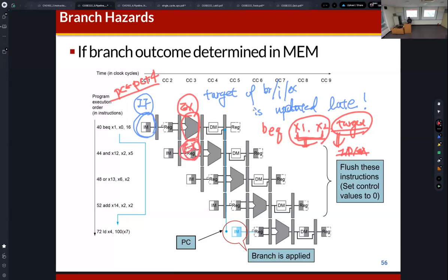But in order to update the program counter immediately, we need to know the next PC in the instruction fetch stage. Because we can know the result of branch instructions late, and if the condition of the branch is true, then the branch is taken, and we need to cancel the fetched instruction.